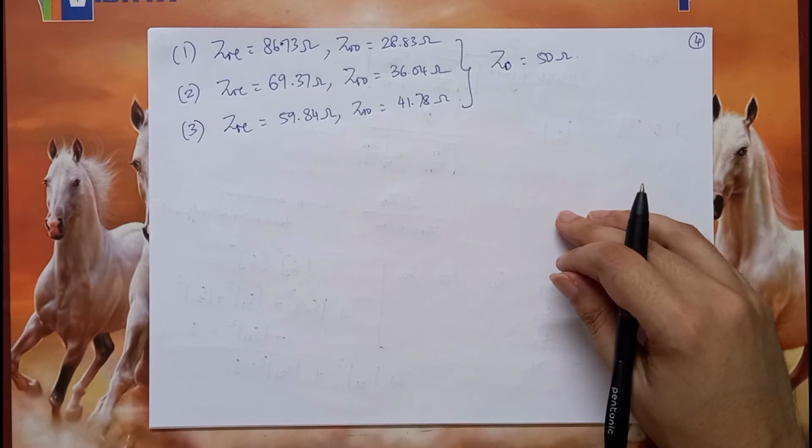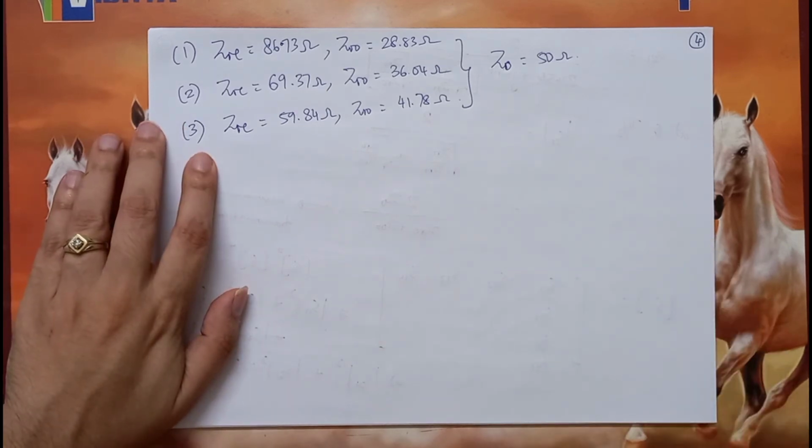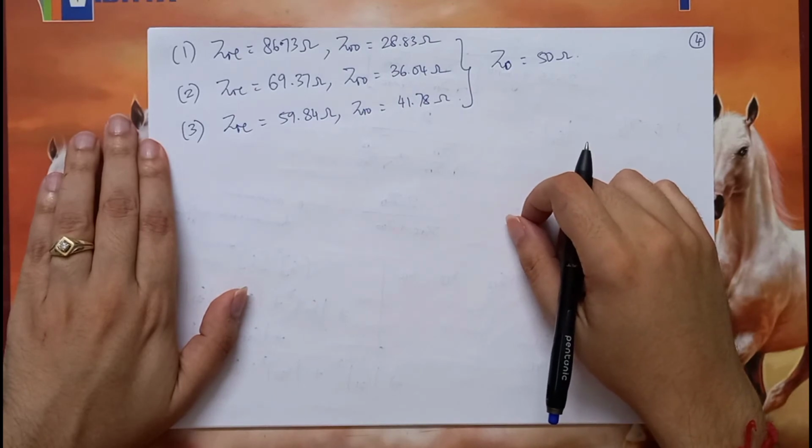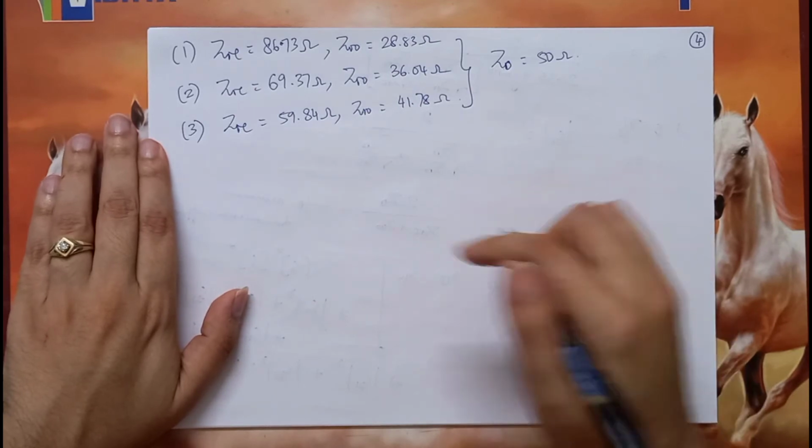Now, much like how we had described in the earlier part of this course that the dimensions of the conductor play a very important role in determining the characteristic impedance of any form of transmission line like microstrip line, strip line or coaxial cable or anything for that matter. Suppose we try to realize these coupled structures in microstrip.